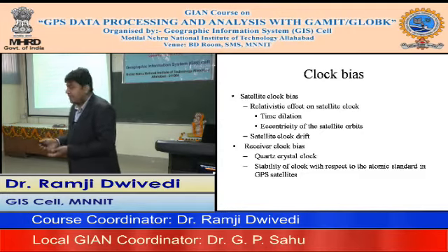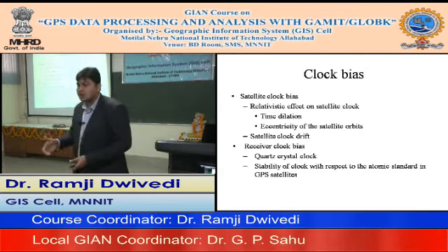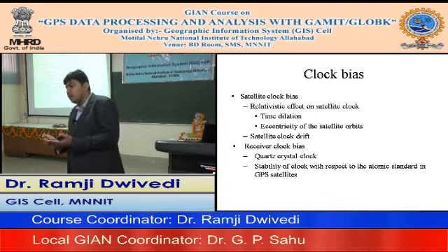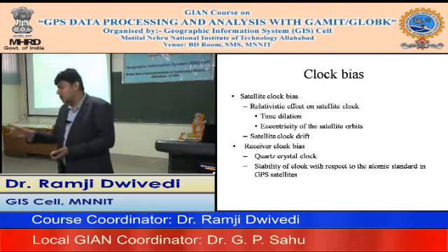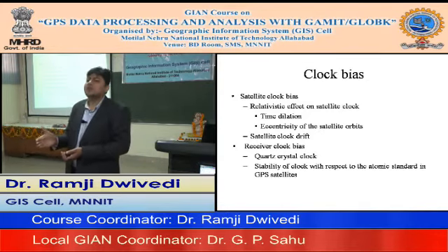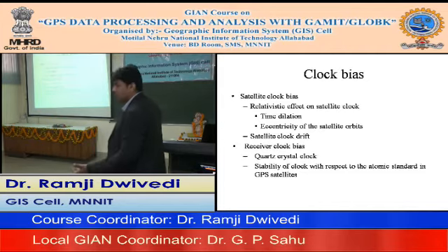One is the GPS time, and we are taking the measurement of time with respect to that GPS time. That's why the satellite clock drift, which is nothing but the permissible allowance, is allowed to drift only 1 millisecond. The clocks at the satellite end are very stable. They don't deviate much; although the threshold is 1 millisecond, they are well within that threshold, and within 1 microsecond of UTC. The clock drift parameters are properly estimated with the help of the navigation message, so this part is properly accounted for when we are measuring the ranges.